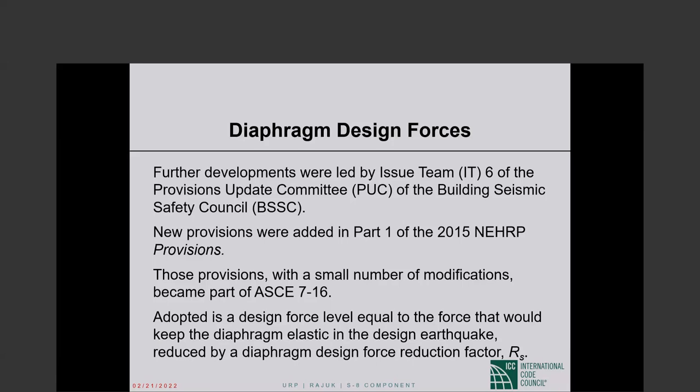That is a necessity. If, from the outside, you want to create the impression there is no gap, you can put something like plasterboard or something that will easily crumble in an earthquake, not interfering with the deflections of the two parts. So yeah, I think you get the idea. You can put something to cover it up, but that something cannot be in the way when the buildings want to deflect. It needs to break pretty easily.